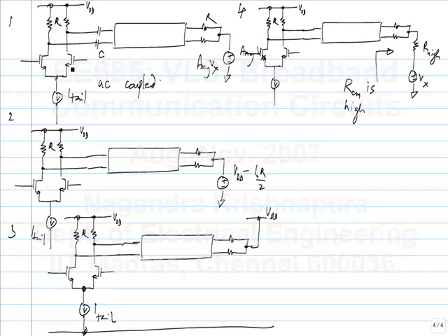Once you have a current source here, that determines the current that is flowing. So there is nothing to choose as far as power consumption is concerned. One thing that we have identified is whether you want to transmit very low frequency signals or not. If that's the case, the first alternative can be more and more painful, meaning you have to use larger and larger capacitors. Especially if you are making a chip, you can't have a very large capacitor on chip.